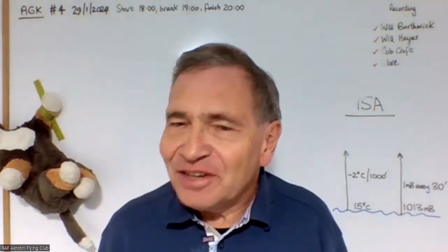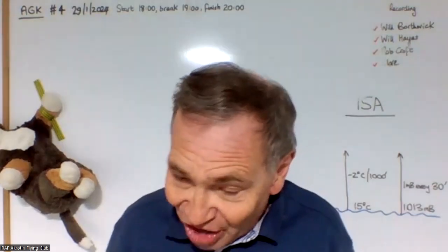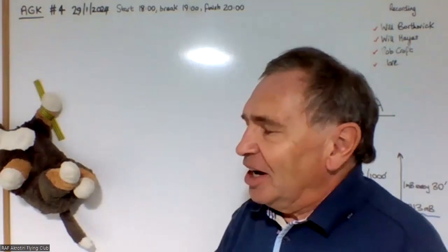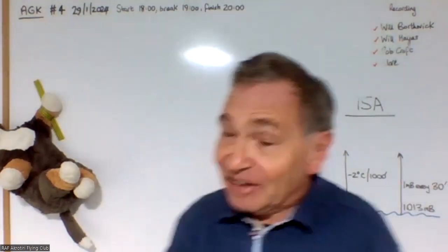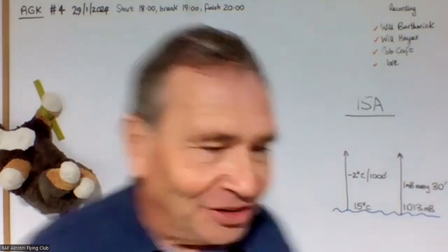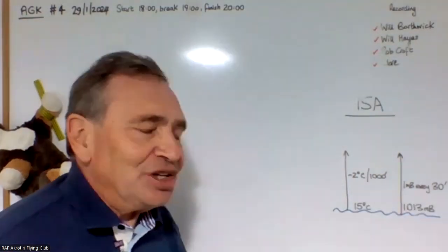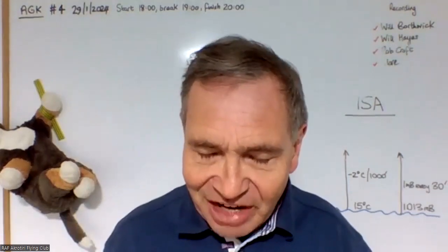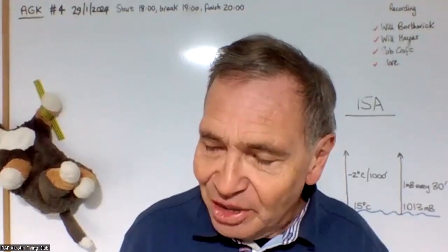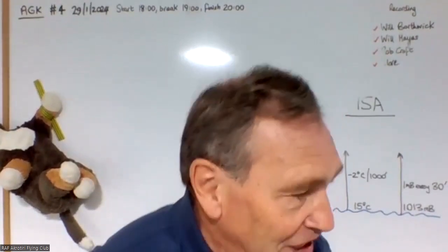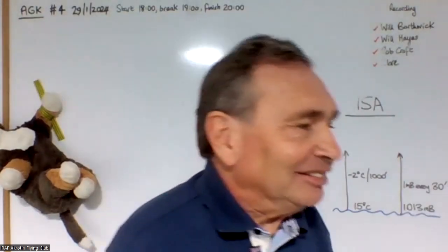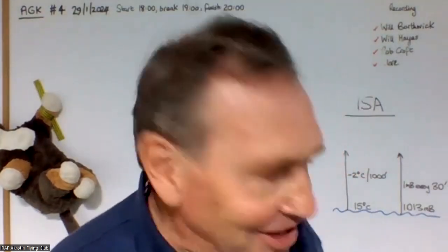So there is no air pressure coming from the Venturi tube, because the Venturi tube has to have quite a high airspeed. The plane has to be doing 30, 40 knots before the Venturi tube is going to start to create pressure. So that means the first time you're going to know that you've got a problem with any of your instruments or your vacuum system is when you're in the air. Well, that's a fat lot of good, isn't it?